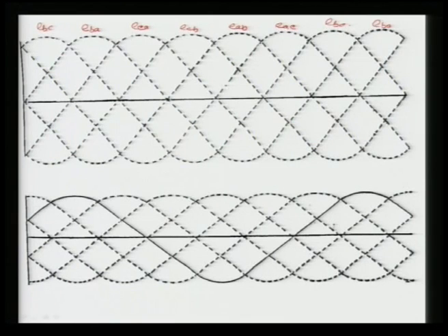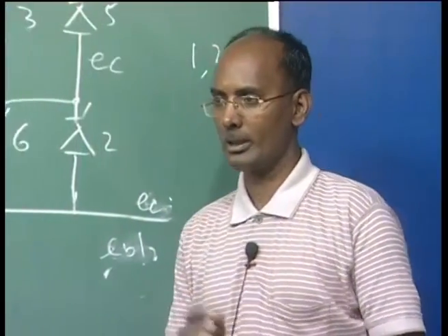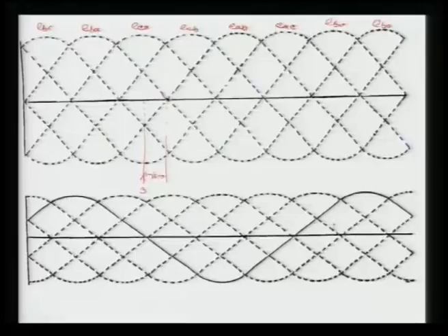Now you can see this EBA is your commutation voltage, and I am taking the condition that valve 3 should be fired, because this is your 0 axis here and this is your beta degree, and I am taking this equal to 30 degree, because this is 60 degree, here this is 60, so it is a complete 180 degree.